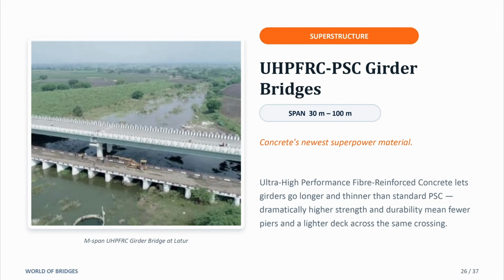And here is a new entry in the span range. UHPFRC-PSC girder bridges spanning 30 to 100 meters. UHPFRC is ultra high performance fiber reinforced concrete, dramatically stronger and more durable than standard concrete, which means girders can go longer and thinner than a conventional PSC section, with fewer piers and a lighter deck for the same crossing.